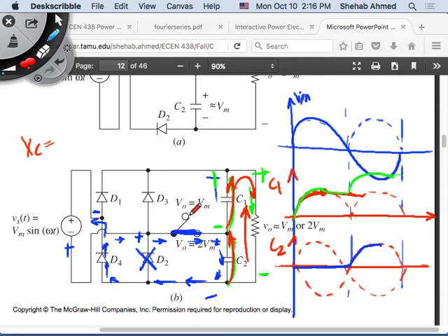So his question is, what's happening to the current flow? The current flow, yes, in the positive half cycle, it's charging this capacitor. In the negative half cycle, fine, it's charging this capacitor, but it's also moving in the opposite direction of the current that was charging this capacitor. It's discharging this capacitor because it has to go through the load. Do we agree?